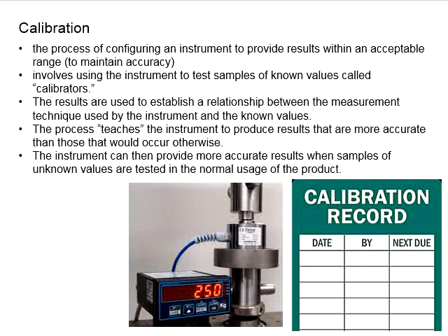Or you may use several load cells, testing over the same known value in terms of the weight. Find the average. Choose the one closest to the average. This is at least so you are confident with your results. And this is provided those measuring instruments are not significantly off from the actual results.